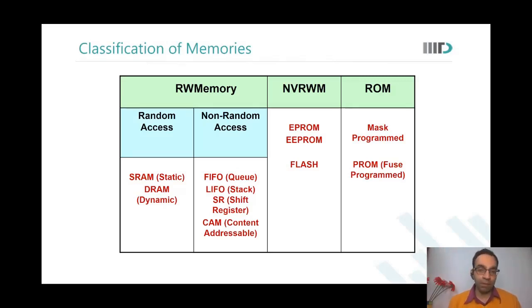Similarly, let us say, in the memory design course, let us say there is some location inside the memory that is failing. I can add some additional redundant memory in the overall chip and say that if this failing location is addressed, then instead of reaching out to that failing location, go to this replacement location. Yes, sir. This again is programmed by using PROMs. Okay, sir. Thank you.